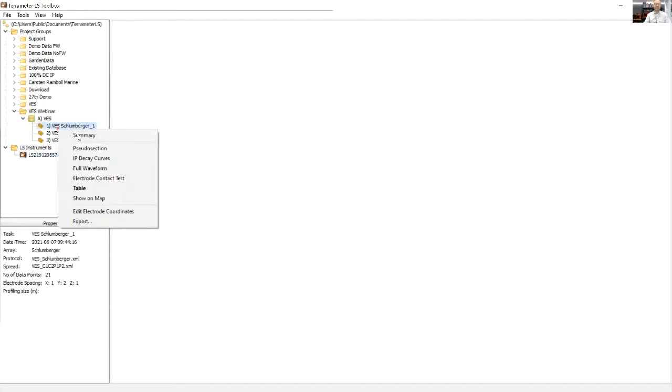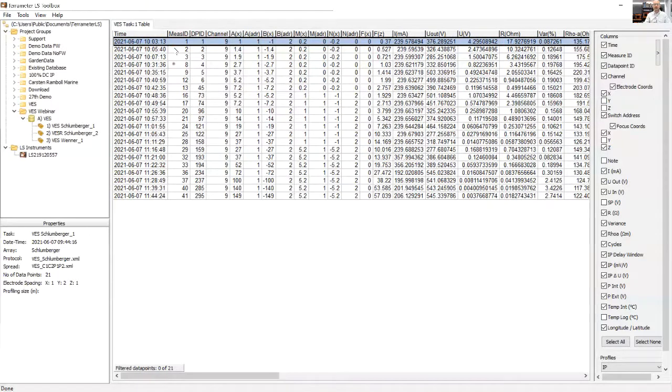So in here, I have a table of results. So I've got time and date, electrode positions in the middle here. I've got the focus depth. I've got the current injected, the voltage pushing that current, the measured voltage, the resistance, which is a calculation of voltage and current using Ohm's law, the variability, how much did it change during the measurement cycle, and then an apparent resistivity.